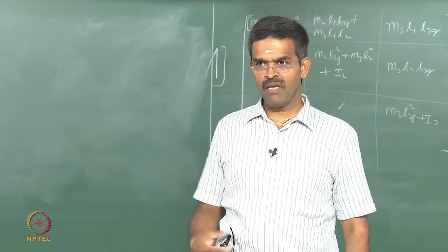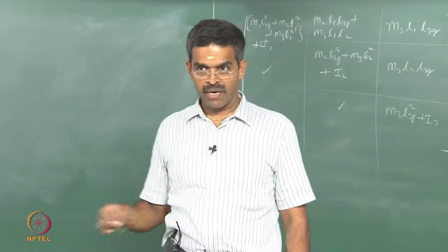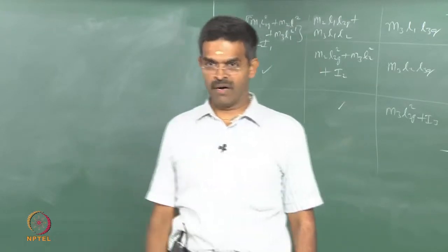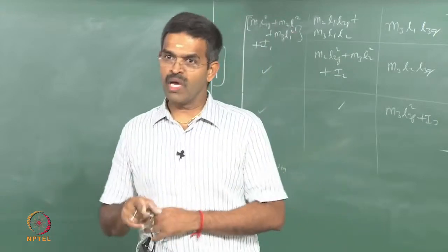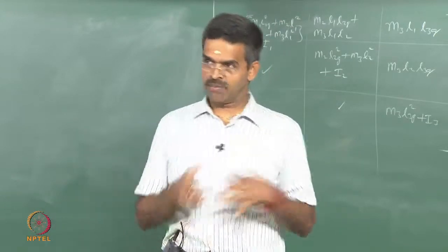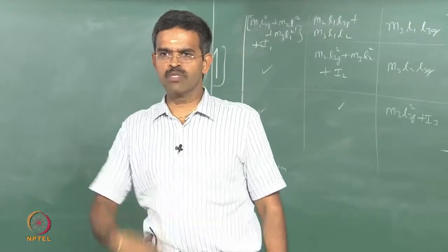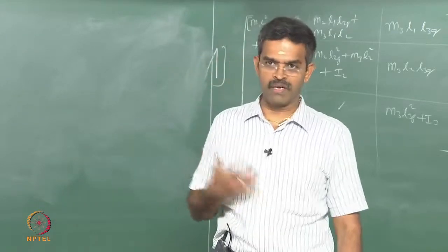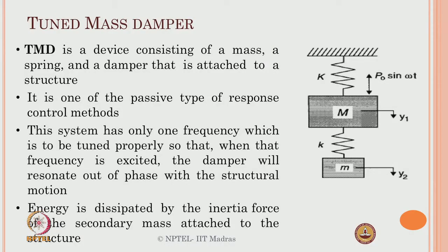So I have to experimentally find the parameter where I tune the secondary mass ratio with respect to the primary mass, such that they not only remain out of phase but I can also get the response experimentally and therefore analytically. What those parameters are, how the equation becomes complicated and so on, we will see shortly, but I want to run a video at this moment and see physically how this happens.